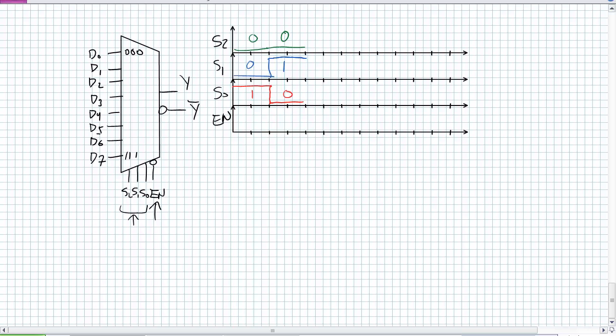You expect it to cleanly transition from position D1 to instantly selecting for D2. I'm here to tell you it doesn't happen that way all the time because, say for example, the LSB position changes first, and then this one changes. Notice the gap there before S2 changes. What am I reading right here? It's 000. It's a glitch.